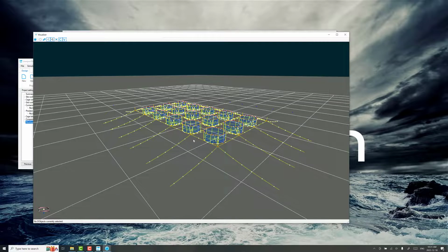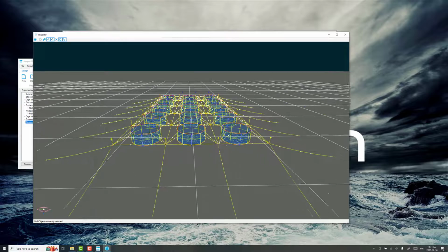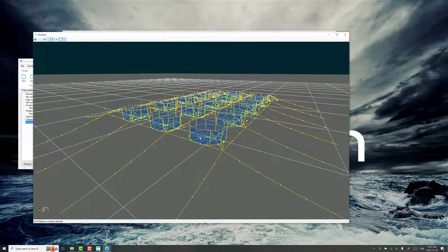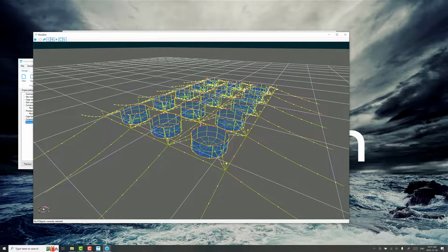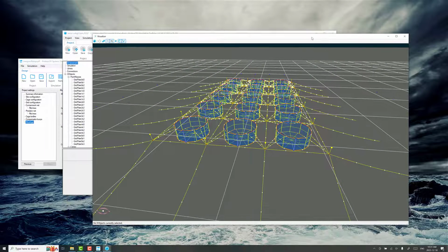But what we really need to do as part of a systematic process is evaluate what happens to the farm in currents and waves. This systematic process starts with a steady deflection of the whole system in current, and then a superposition of the wave load effects on that. But it's not just one case. Usually standards require evaluation of the mooring loads in many different weather headings as well. So we want to show you how to do that.